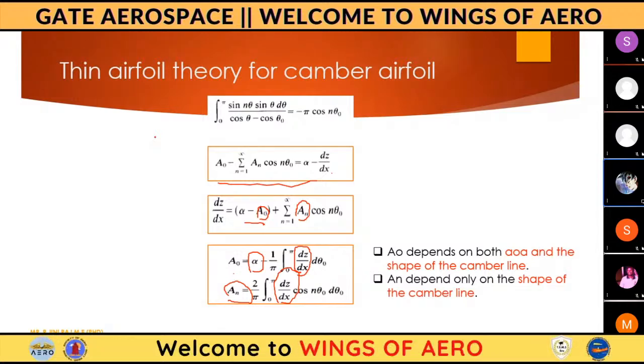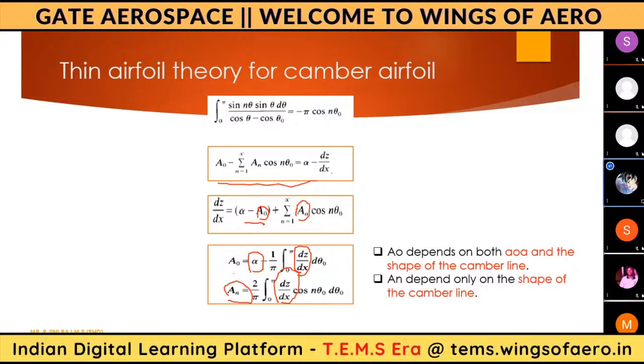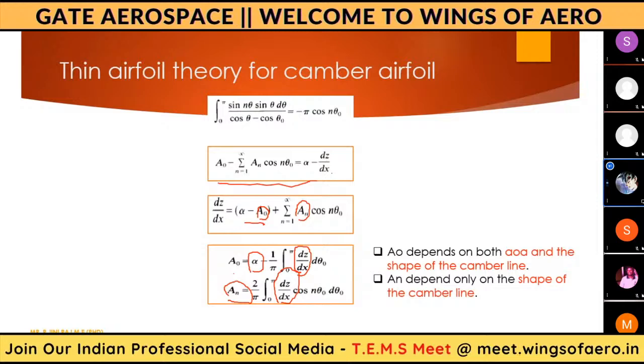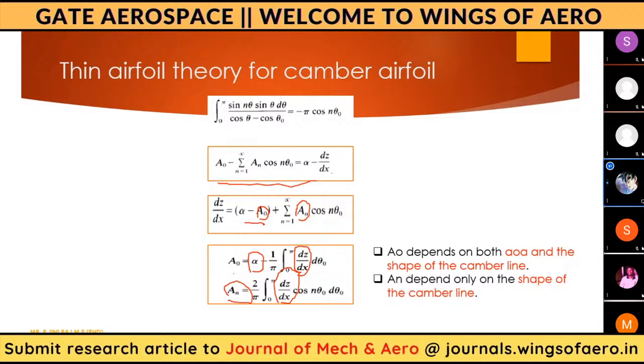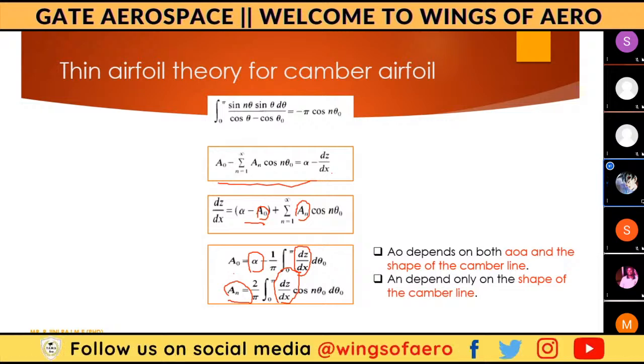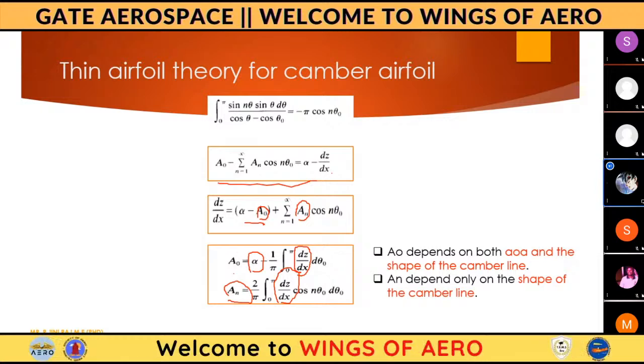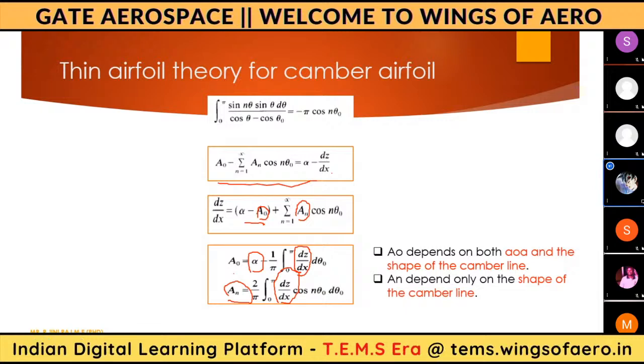Okay, fine. So the question they are asking is the moment about the leading edge when the condition is zero lift condition. The angle of attack will be positive, sir? No, it is negative. It will always be negative, because for a zero lift angle of attack the value is negative. So the pitching moment coefficient value will also be negative only.